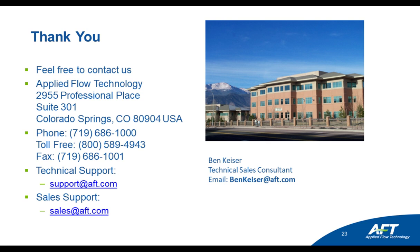That's definitely a very big deal. I mean, the case study there made it really clear that when they were operating all of their pumps together, they thought that they needed 4 or 5 pumps operating in parallel all at once, and they really didn't. And when they were operating all the pumps, the expectation is that the pumps together should deliver more flow, where in reality it doesn't.